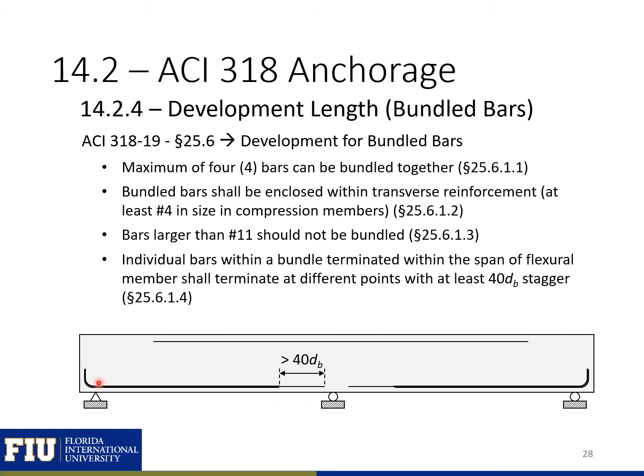So if I have bundled bars here and I'm going to terminate one within a span, I need to make sure that I stagger the termination of those bars by at least 40 times the diameter of that bar.